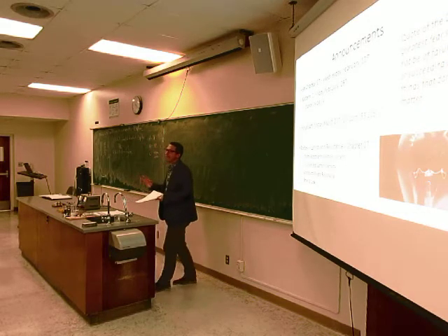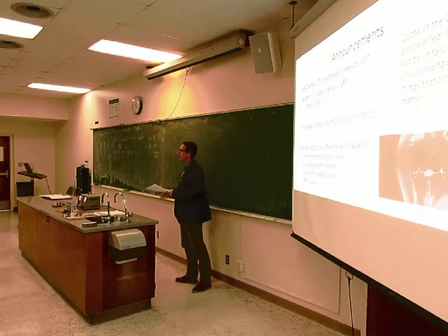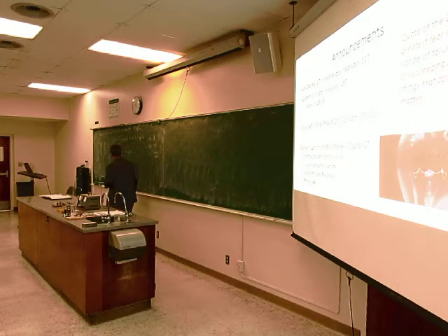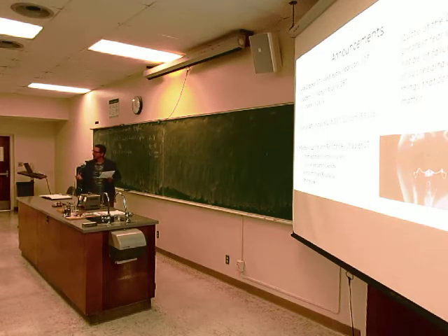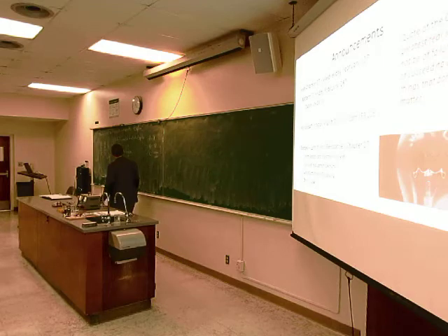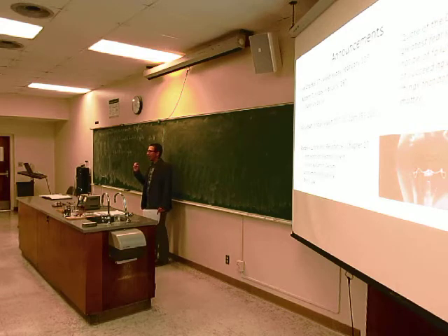Now, one of the assumptions we're making here is that this fluid, or this sea of conduction electrons, is incompressible, right? Now, in reality, what happens is when you close the switch, there's going to be a wave that propagates very, very quickly, like a ripple in the electric field. Imagine if I shake a rope and that pulse travels through it, basically turns it on. But that's almost instantaneous. Why does a light bulb glow to begin with? Well, it takes a certain amount of time for it to heat up. Since those time scales are very, very small, for all practical purposes, we see them light at exactly the same time.